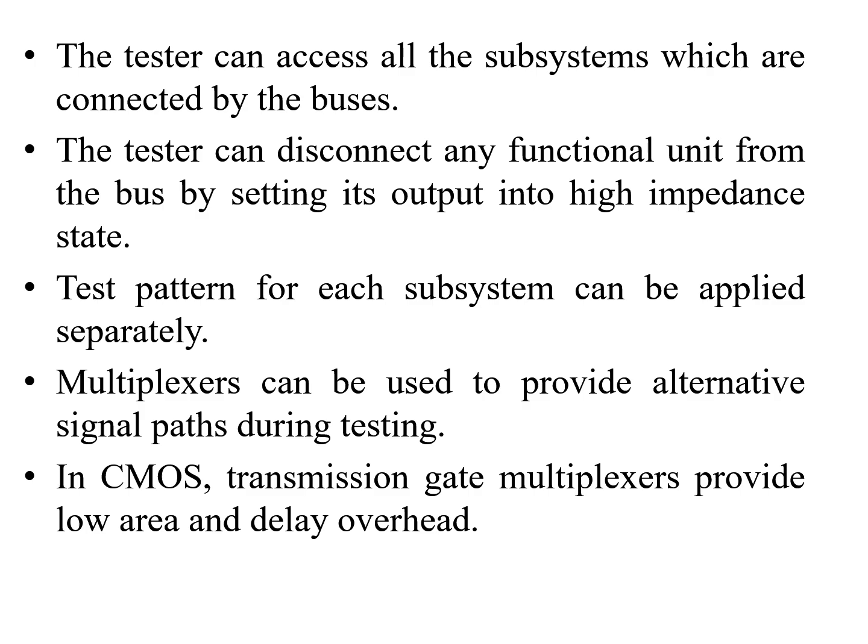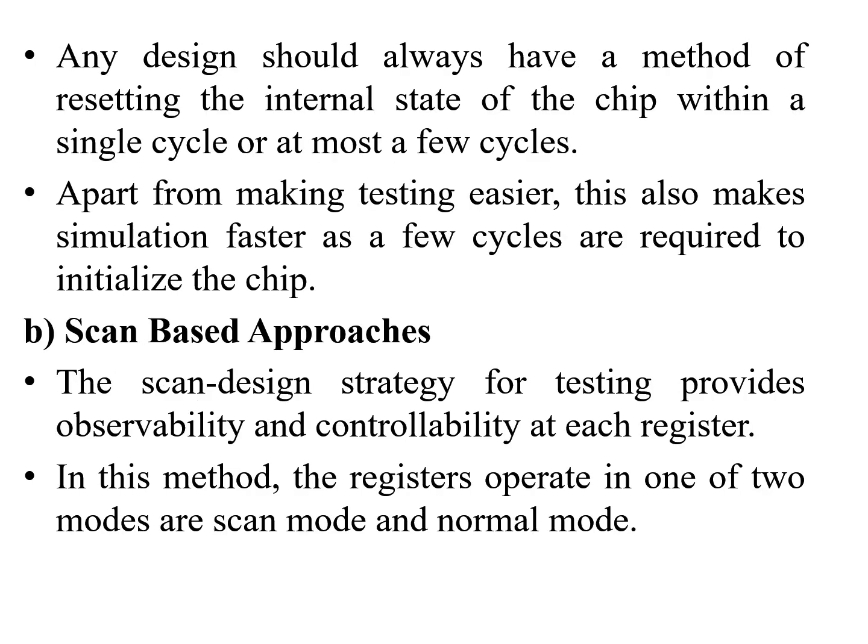Multiplexers can be used to provide alternative signal paths during testing. In CMOS, transmission gate multiplexers provide low area as well as reduced delay overhead. Any design should always have a method of resetting the internal state of the chip within a single cycle or at most a few cycles. Apart from making testing easier, this also makes simulation faster as a few cycles are only required for initializing the chip. Scan-based approaches. The scan design strategy for testing provides observability and controllability at each register.